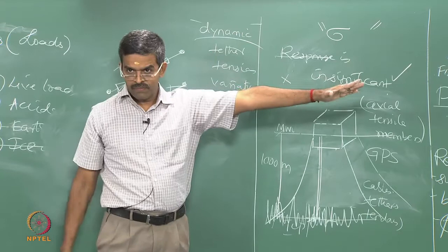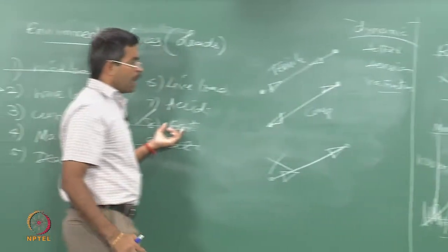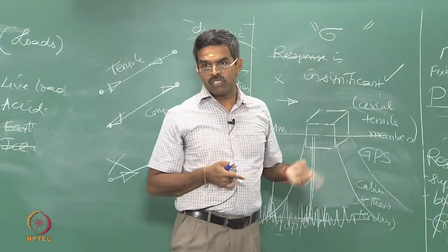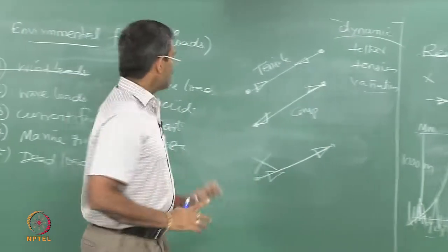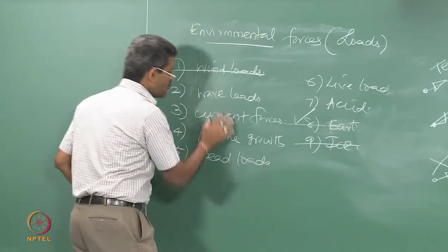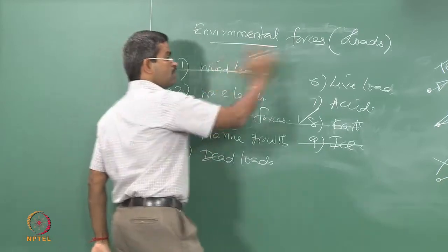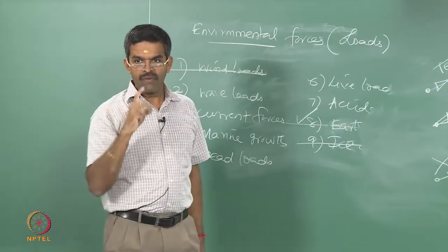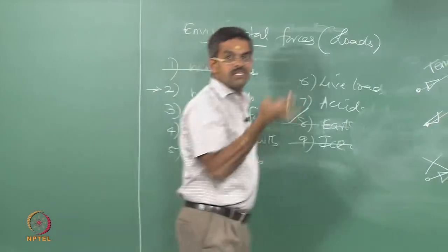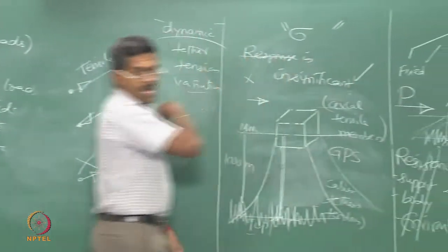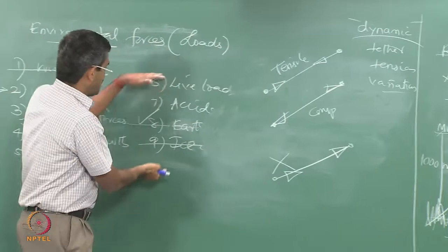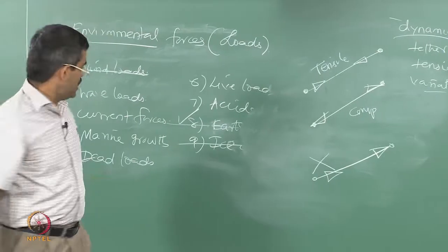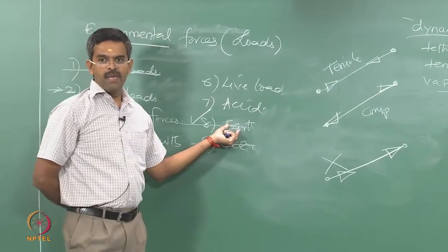In all the three cases, earthquake force applied to a variety of platforms imposes a variety of structural reactions, which is not common. So, what we try to understand here is not the force alone, but the effect of force on the system, which we call dynamic response analysis. So, the variety does not come from the force, the variety essentially comes from how these structures behave for these forces. So, if there are 10 varieties and 3 platforms, you have 30 combinations. I have taken a specific example of how they behave.